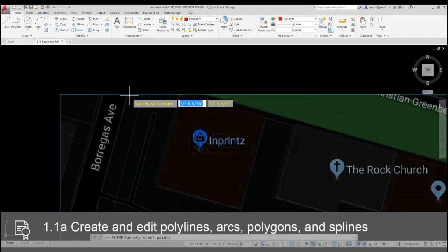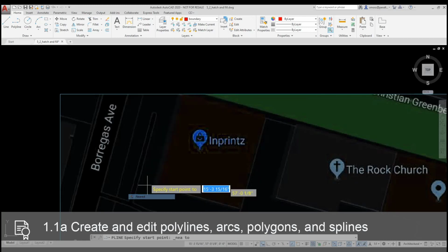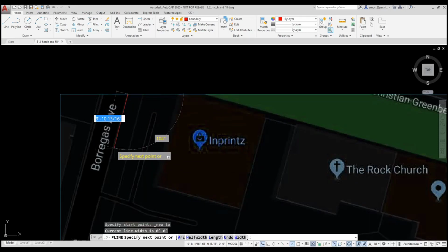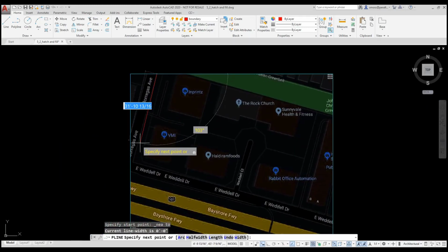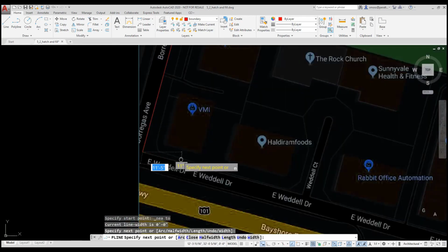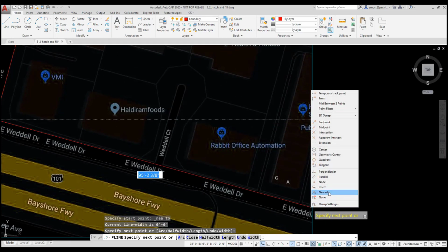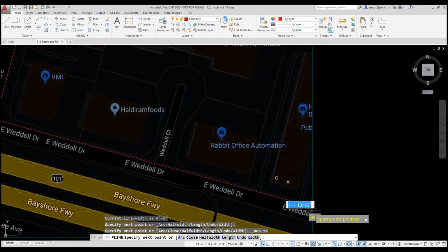I'm going to draw the boundary for my hatch. I want to indicate where bike lane striping needs to be placed for a subcontractor. I use the Polyline tool to draw the boundary. I can snap to the outline of the PDF to complete my boundary.